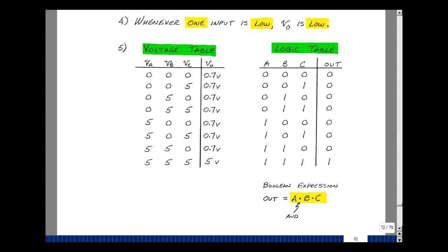Let me give an example where we might use something like this. Let's take a battery again. And I have 3 switches now, but they're in series. With a light bulb. These are called normally open switches. When you press the switch, it'll close it. Suppose now that when a door closes, we close the switch. One door closes, the light doesn't light. I would have to have all 3 doors closed before I'd light the light. Maybe use this on an airplane. If the doors in the airplane are not closed, don't start the engine. And these are diode logic circuits.